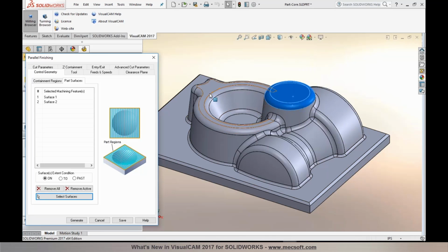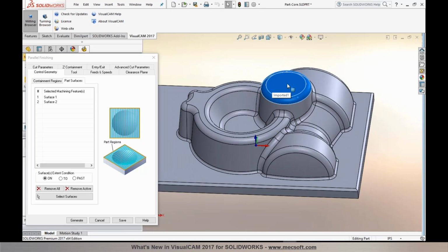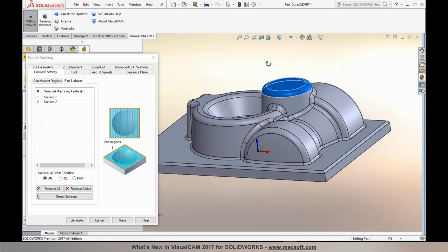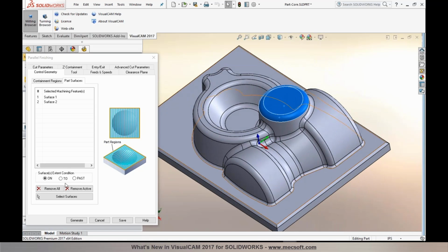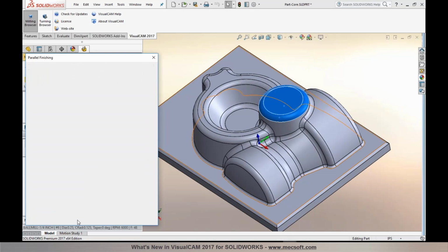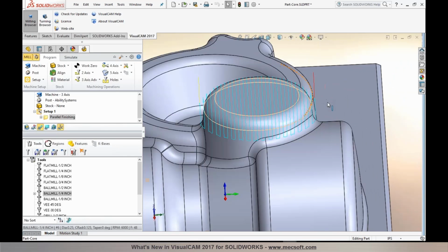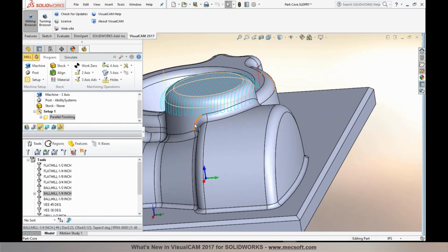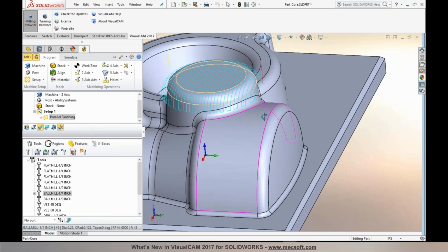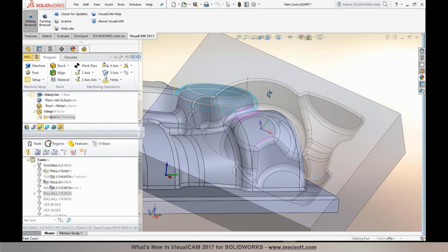Yes, Joe, I believe so. So I pulled in the same part that we were demonstrating for the surface selection. And I'm going to set the condition to be passed. And in this particular case, as you pointed out, it is checking against all of these adjacent surfaces in here to ensure that the tool isn't gouging the geometry, the toolpath isn't gouging the geometry.